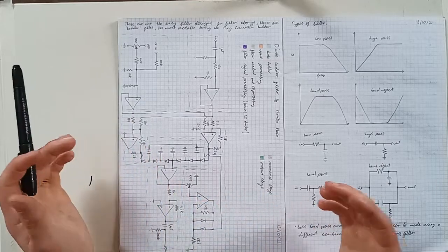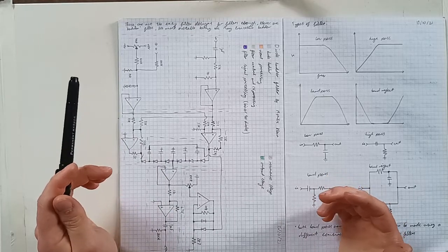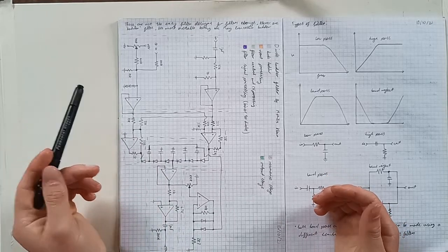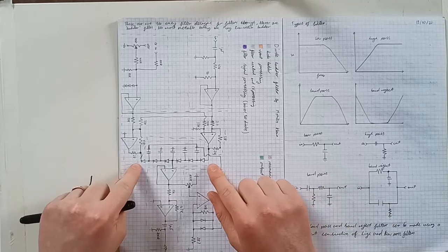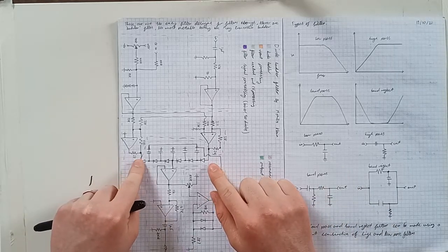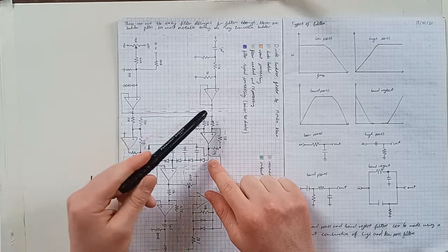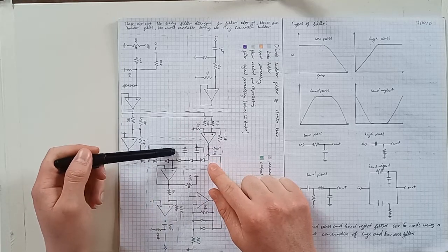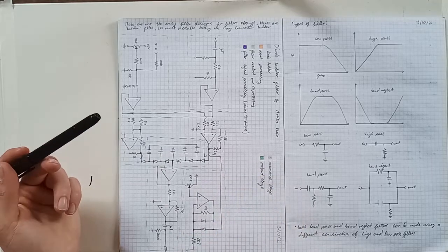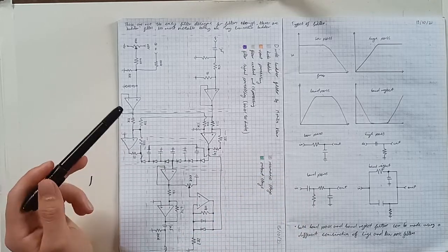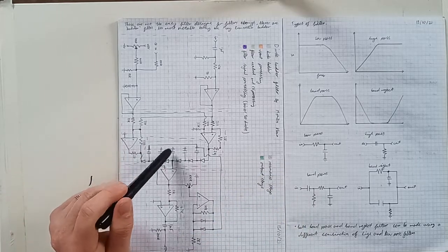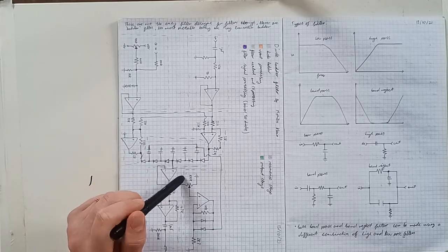And then that would give you your high pass filter. And to then get a band pass, you would have, just like your low pass here, your biased signal going into each end, but you would then also connect it to the central capacitor like in a high pass. And that would give you a band pass, but it wouldn't be at the same order of the individual low pass or high pass.